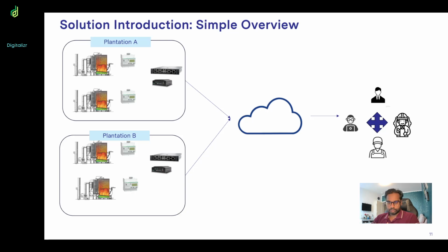Within this industrial PC, there is software pre-configured to read the data through the Modbus communication protocol. By doing so, we have attained the data, and on this industrial PC, we're going to work on how to send those data to a publicly available cloud service.